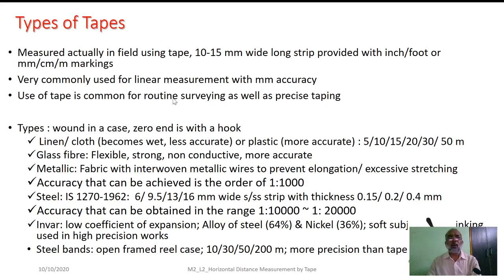As far as routine measurements are concerned, as far as precise measurements are concerned, tape is a very versatile tool to measure the linear distances. Usually, this tape is wound in some kind of case with its zero end provided with some kind of hook.